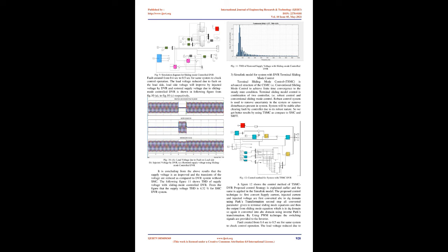In the proposed control technique, supply current, injected current, and injected voltage are first converted from ABC to DQ domain using Park's transformation. Second, all converted parameters are given to sliding mode equations, and the output from the sliding mode equations, which is in the DQ domain, is converted again into the ABC domain using inverse Park's transformation. By using the PWM technique, the switching signals are provided to the inverter.